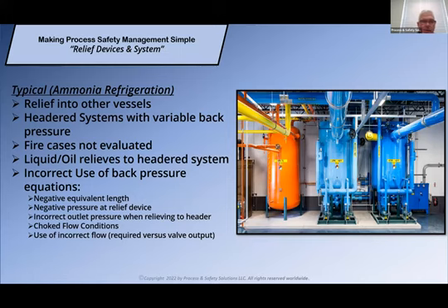And even then you have to look at that equation from the standpoint of, do you have any changes in diameters, et cetera? If some of those things are negligible, it might be okay to use, but keep in mind that if this is a headered system, that equation cannot be solved directly. It has to be iterated at the different points within the system itself.